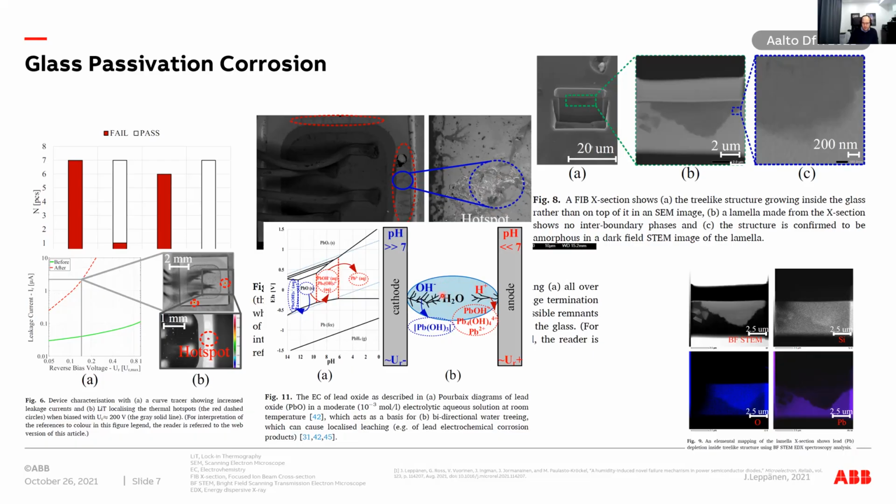But on the other hand, we also consider that this area where the lead has dissolved is less insulating than the original glass, and that will cause the breakdown also. But nevertheless, this is one interesting topic, and this was something new. We didn't anticipate this kind of a phenomenon, and I was really surprised to see this kind of an issue.